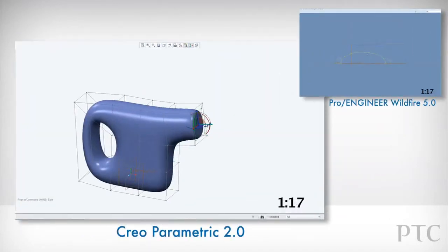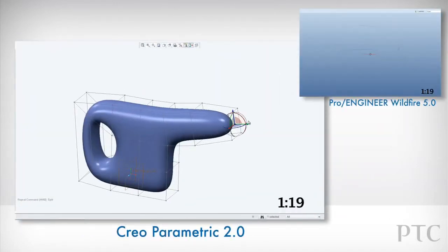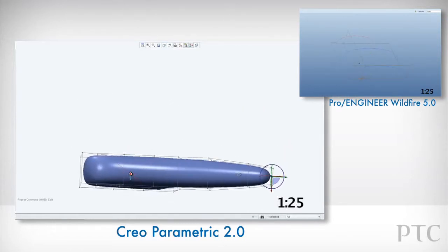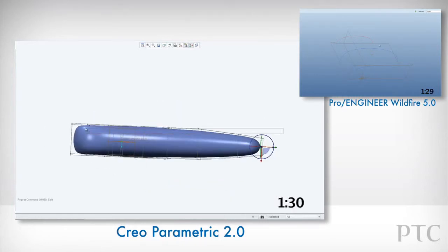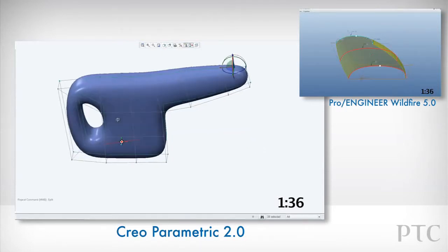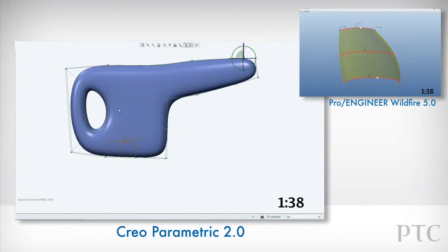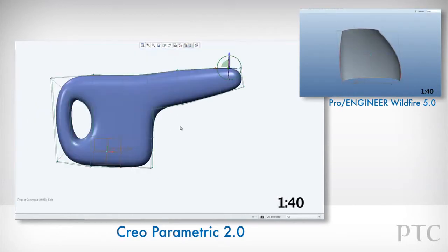Back in Creo Parametric, we're going to create the neck of the watering can. We can add geometry and then use the Split command to add finer control on the way. Since we're designing a product that's symmetrical, we can use the Mirror command. After selecting the mirror plane, half of the control mesh disappears. Any change that we make along the neck is mirrored to ensure a symmetric part. It's also possible to locally break mirror dependency.